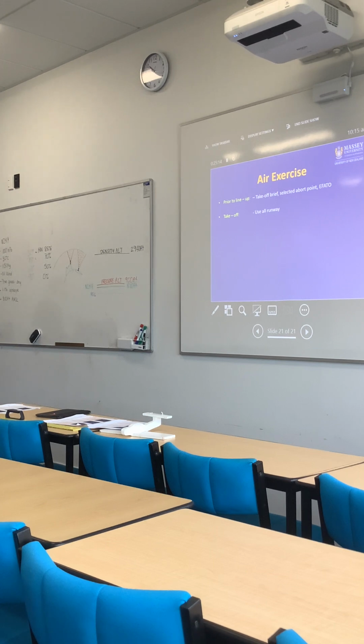So we will use all the available runway. Once we've done our line-up checks and we've been cleared for takeoff, or we've done our takeoff call, we'll apply full power. If it's a stony surface that we're taking off on, just caution for any stones. You may want to increase the power just slowly and keep some aft elevator on. Your feet should be firmly on the brakes at this point because we want to maximize the acceleration. We can reduce the takeoff roll by first setting power and then releasing the brakes once full power has been set.